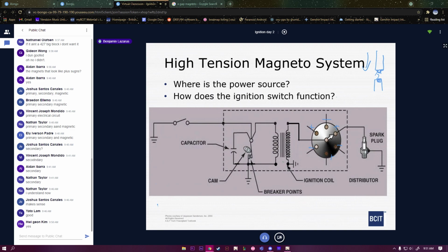In an airplane, when the manufacturer makes a spark plug, they have no idea if it's going to be, we'll call it, a positive polarity spark plug or a negative polarity spark plug. So this is going to cause a wear issue with our spark plugs, and this is kind of delving into the next lecture. But what we do is every 100 hours or every annual, when we take our spark plugs out, we take the spark plug from